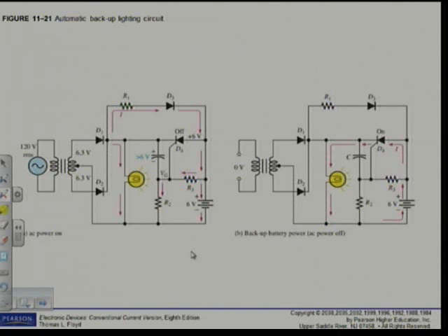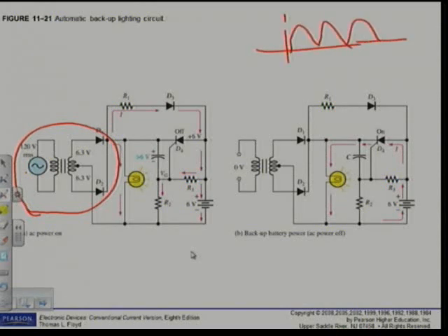In S1 you did a full wave rectifier making use of a center tap transformer. Here we got exactly the same. If you look at this part of the circuit, we got a transformer, we got our AC supply, we got a center tap transformer, we got two diodes D1 and D2, and that will give me basically the following output. That should give me an output that's going to look like this. We will have a DC voltage. That will be 0. That will be my V peak. Alright. I will have a DC voltage from my AC supply.